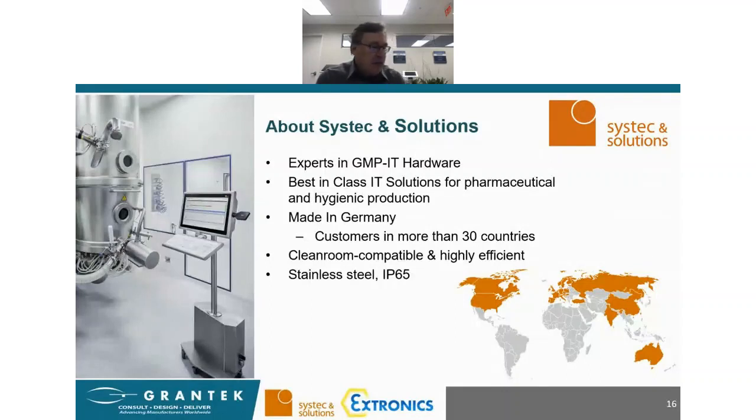They are IP65. People talk about IP ingress protection, and 65, the numbers have to do with the protection of ingress of liquid or dust and particles, which is important. But what's also important is anything that stays on the outside and even doesn't ingress, is you have the ability to wash it down, wipe it down, clean it, and make sure you're not getting any cross-contamination. And when I show them to you, you will see they're designed absolutely for that. Smooth, rounded corners, polished stainless steel. Very difficult for any entrapment to occur.